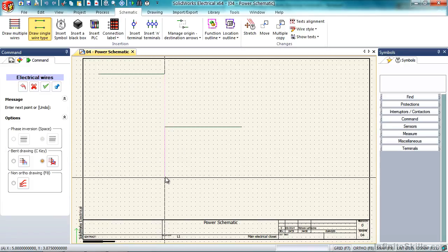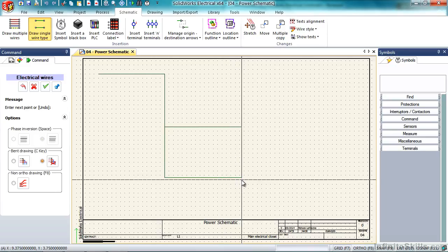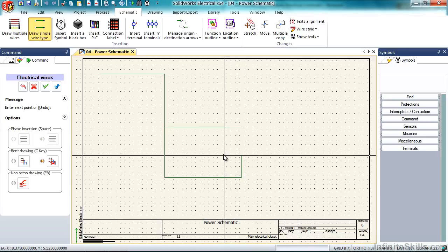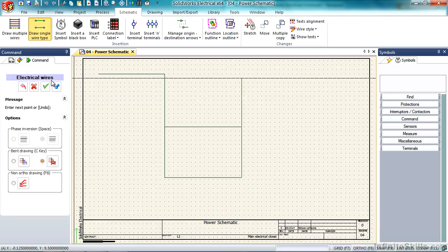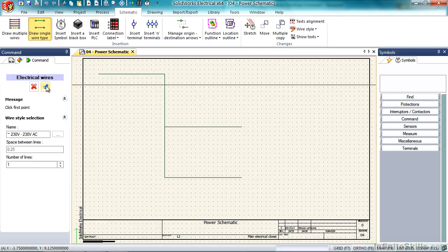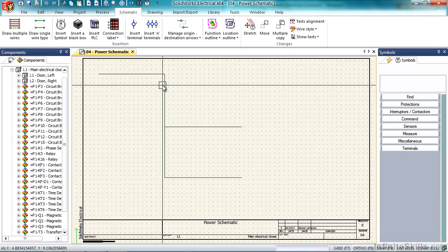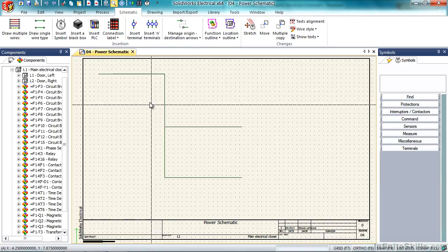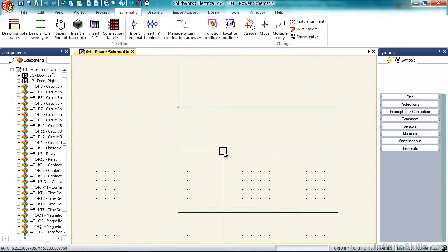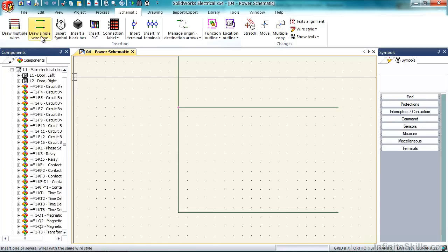If drawing another wire connecting to another wire, as we've done here, and then right-clicking to end the drawing segment, you will notice that we will have a connection dot available where the wires form a junction. This only appears after you close out of the drawing command. As you can see, we have the gray dot available. This was placed automatically by the software.